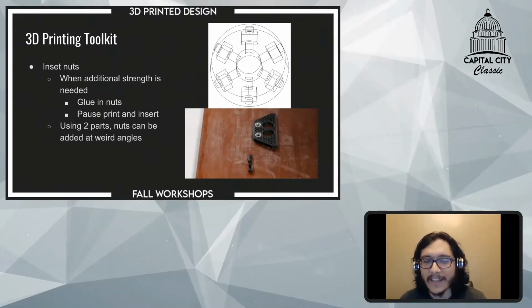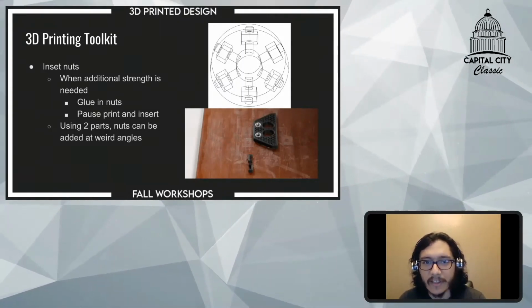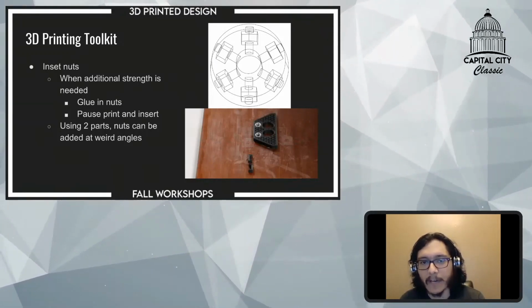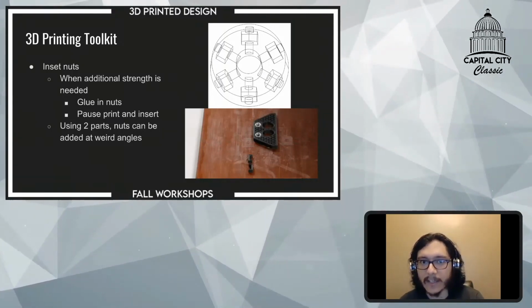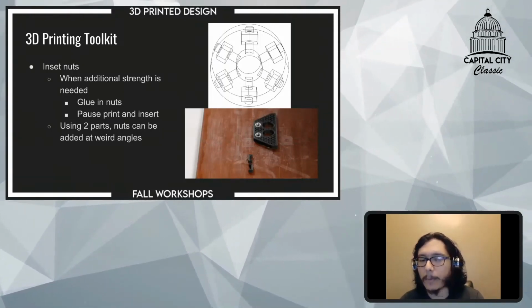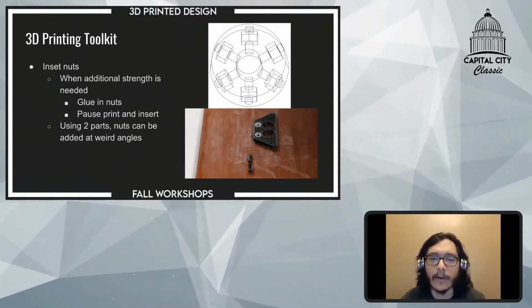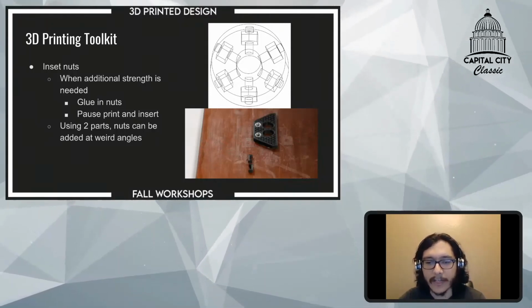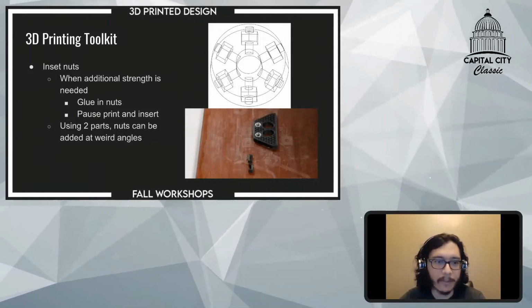If you look at the top right picture, you see those square features. We actually slid nuts all the way into them, and then we had holes that came out radially. And in the pipe, we drilled and put bolts through so that you can transfer a high amount of torque. I believe on the other end, it's not shown here, of this plug, there was a pulley. So we're actually able to support our whole elevator and transfer power to it through a 3D printed part.